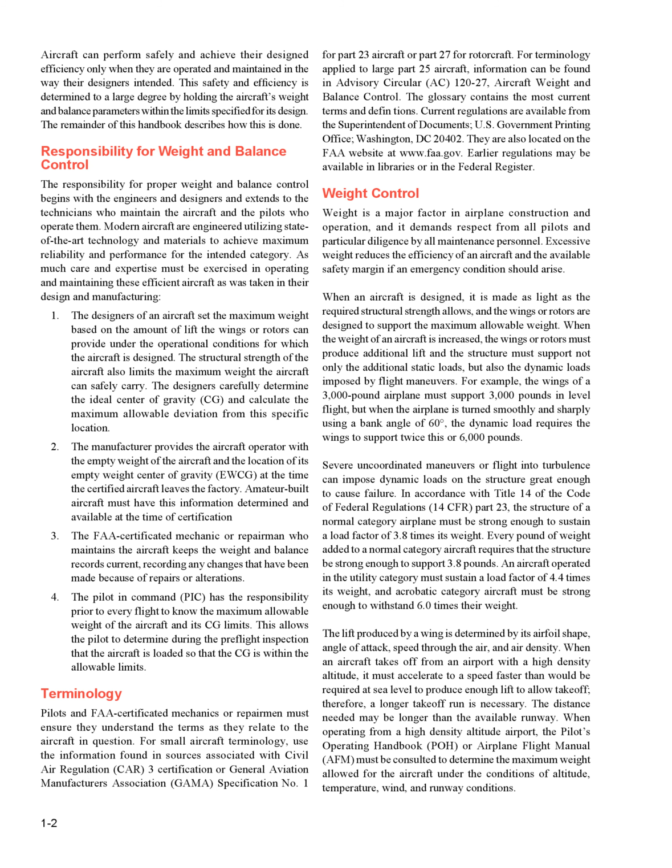1. The designers of an aircraft set the maximum weight based on the amount of lift the wings or rotors can provide under the operational conditions for which the aircraft is designed. The structural strength of the aircraft also limits the maximum weight the aircraft can safely carry. The designers carefully determine the ideal center of gravity (CG) and calculate the maximum allowable deviation from this specific location.